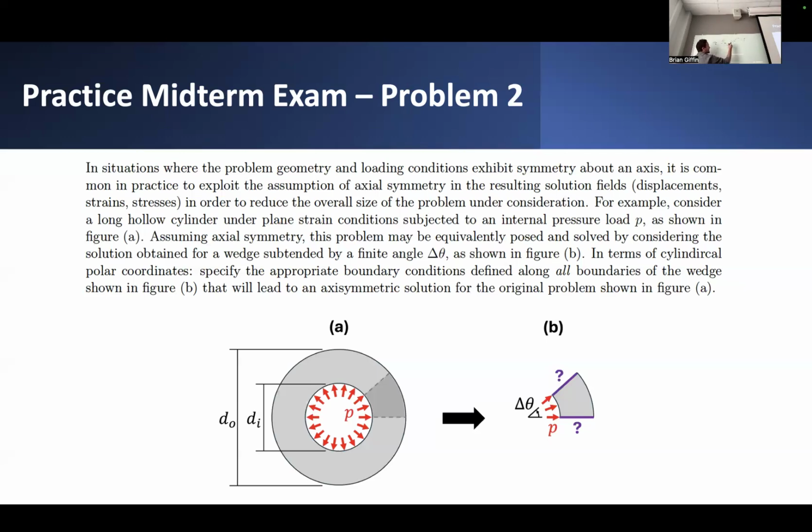So we'd have basically a sigma R theta component of shear traction that acts in this direction. And it would have to be balanced by basically an equivalent value here. And then by similar arguments, we can rationalize that really it's the same component of shear stress that acts on all of these four different faces.